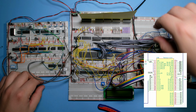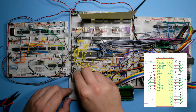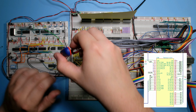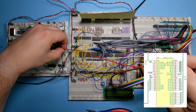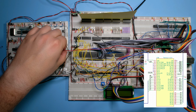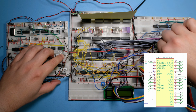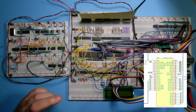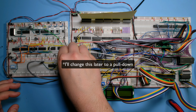It's currently connected to the clock in pin. So I will get clock in from here instead. And then we need clock enable. And clock enable is on pin 7 here. So we need to remove this jumper to ground. And we can connect that directly to the Teensy. And actually I should probably add a pull-up to this pin. If there's an issue with the Teensy that it is not driving the clock enable, we don't risk creating a conflict where both of them are driving the pin at the same time, just as a safety. So for that, I'll just use a 10K resistor to VCC.